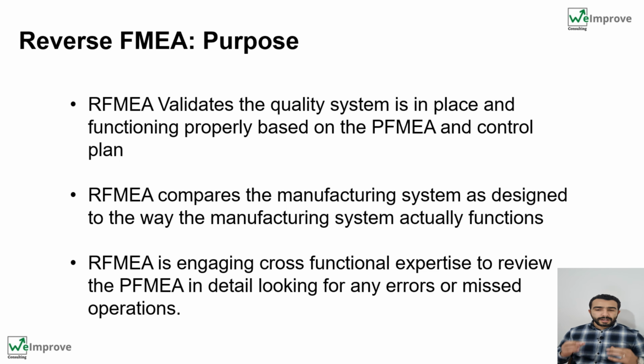It means that after you implement the FMEA in the process and production is running, you have to go into your process and check whether what you considered previously as control plan, detection mode, severity, risks and so on is exactly what is in your production right now or not. It's like you are making an audit, checking whether what is in reality matches what is in your documentation and what you put as assumptions in the beginning.